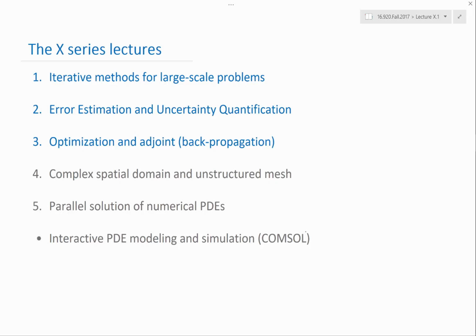And there is potentially one lecture on using COMSOL to interactively model problems using PDEs and solve them without much coding by yourself. You still need to derive the weak form because COMSOL is based on finite elements. So for every problem, you have to know how to derive the weak form, how to integrate whatever boundary condition you have into the weak form, and whether it is an essential or natural boundary condition. But once you have the weak form, you can basically give it to the software and ask COMSOL to solve it.